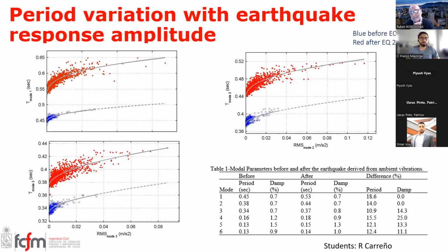But one of the nice things when you have a lot of shaking is that you can monitor things like, for example, let's take this image. This is the displacement of the roof as a reference. And this is the first mode period. This is before the 2010 earthquake, and this is after. So the jump from here to here is damage, an 18 or 20% period change, meaning that during the earthquake, the stiffness changed around 40% because the mass didn't change too much.